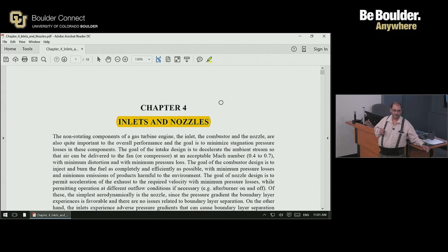Now, one thought is that the way the engines are mounted on the wing, whether it is the fan casing that is attached, or the body of it and things like that. They had a problem with this mounting because the casing has to remain circular. If it deforms, gets an elliptical shape, then of course once again blades can touch the casing.